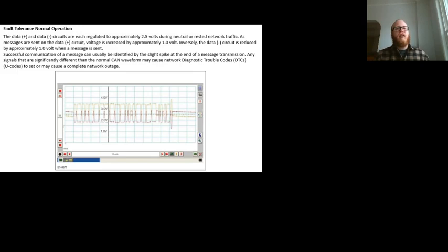All right, so now is the time, if you want to pause this or whatever, let your brain cool down. We're going to look at the actual waveform captured by an oscilloscope of an active communication network. So this is a high-speed network. Our y-axis is voltage, and you can see we're up in positive voltage. Our average is around that 2.5 volts like we talked about before.